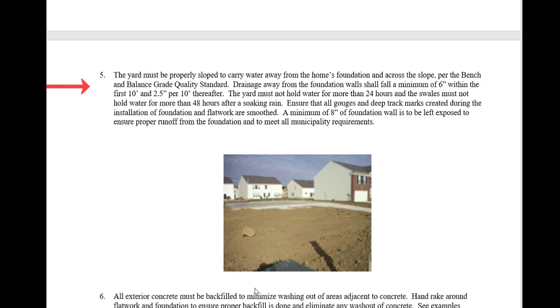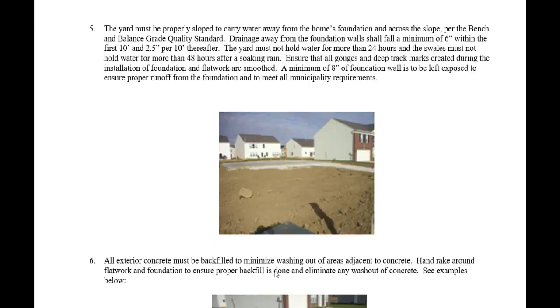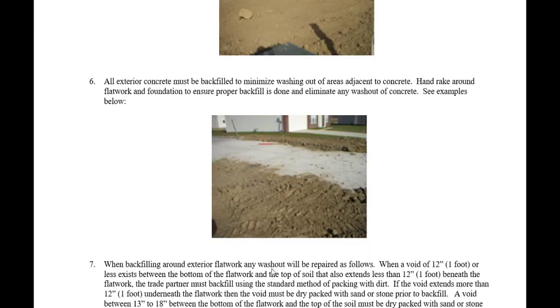Ensure that all gouges and deep track marks created during the installation of foundation and flat work are smoothed out, and a minimum of 8 inches of foundation wall must be left exposed to ensure proper runoff of the foundation and to meet all municipality requirements. All exterior concrete must be backfilled to minimize washout of areas adjacent to the concrete. Hand rake around the flat work and foundation to ensure proper backfill is done and to eliminate a washout of concrete.